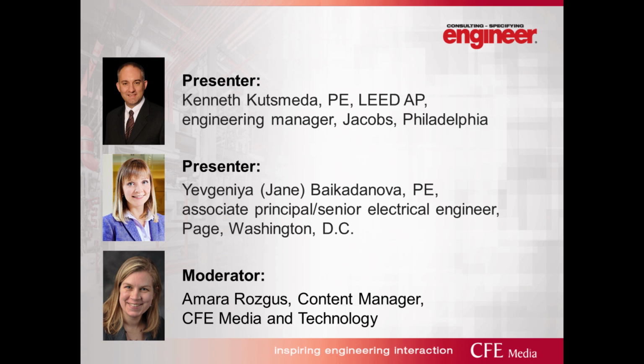Again, in most commercial applications we see switchboards. For critical facilities like data centers or healthcare facilities, like hospitals, where continuity is very important and you need to have a fully coordinated system, you would pick a switchgear, because that 30-cycle rated gear allows you to coordinate better with the downstream devices. So if a fault happens somewhere in one of the branch panels, it's not going to disconnect the main breaker that feeds that branch panel. So you're not going to lose a lot of loads, just the one that had a fault.